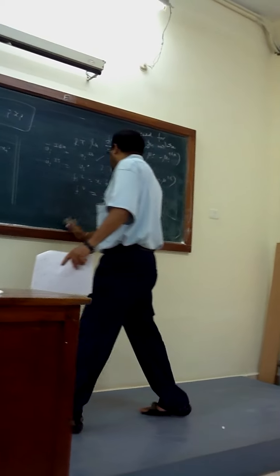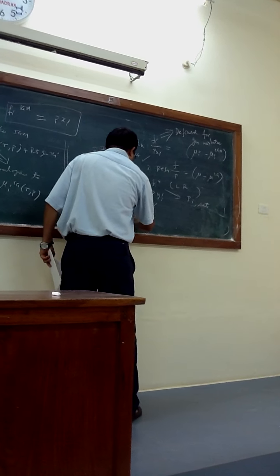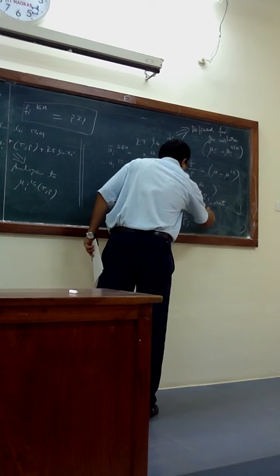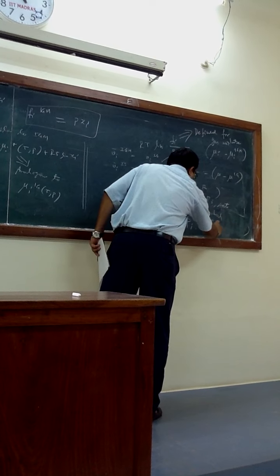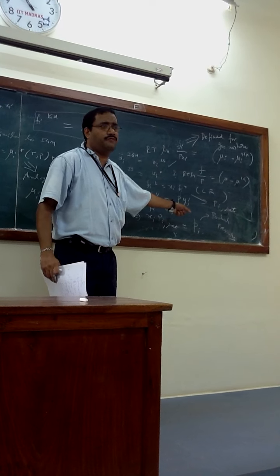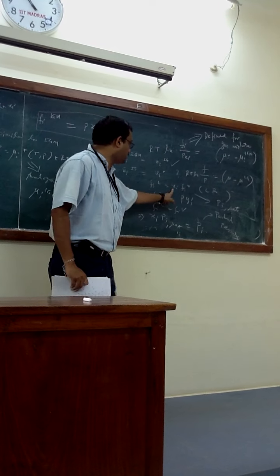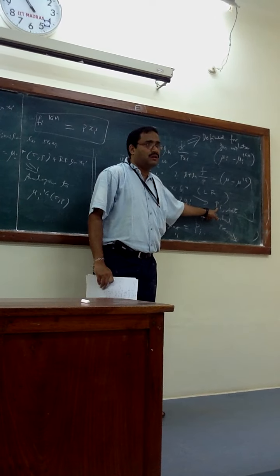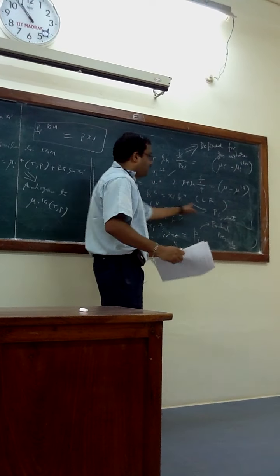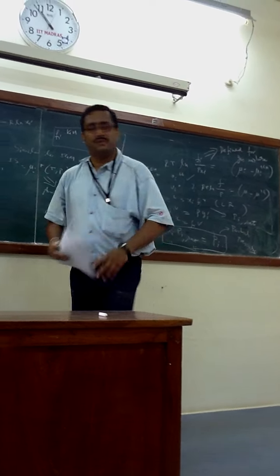Okay, so when f_i^L equals f_i^V, which is nothing but x_i P_i^sat equals p_i, which is the partial pressure. Partial pressure denotes the gas phase. Partial pressure is not defined in the liquid phase. It is nothing but x_i P_i^sat, saturation pressure, which is obtained from your Poynting correction or whatever. In this diagram, whatever we have, we have proved something, right? So this kind of thing will give P_i^sat, and this is nothing but Raoult's law. Thanks for kind attention.